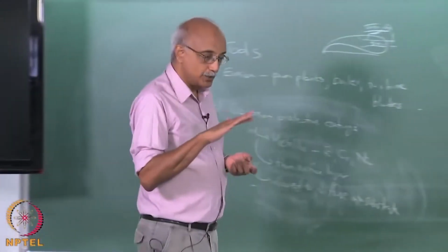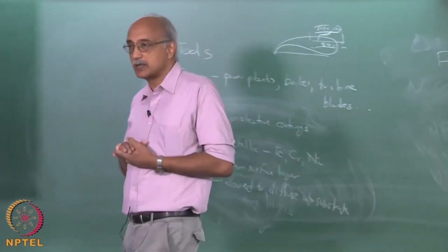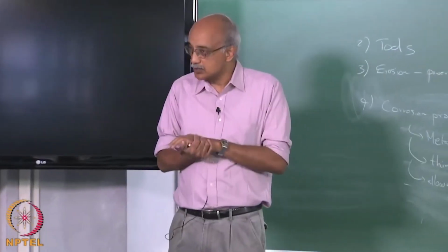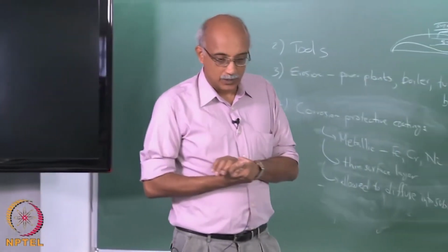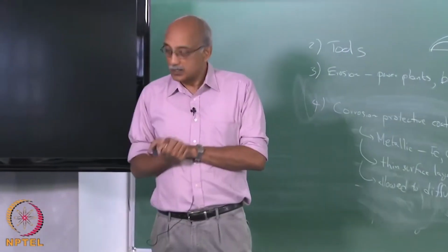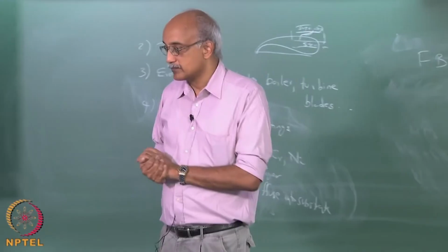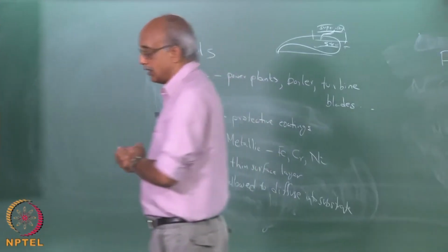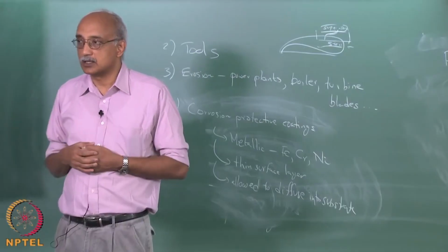So, it certainly makes sense to put down a coating on a polymer, and it is very difficult to do because plastics by definition are low surface energy materials, and so adhesion tends to be poor if you put down a coating, and also the chemical reactivity is also not very strong. And so, conventional coating processes do not work very well, and even conventional CVD processes do not seem to work too well. It is very difficult to get a CVD film to bond onto polymers, and also you cannot use high temperatures because most plastics will degrade, most polymers will degrade at high temperatures.